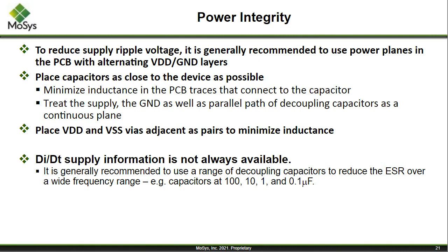And in most cases these days, I think if you look under any of the FPGA boards put out by Intel or Xilinx or anybody that's out there, people are putting capacitors literally under the device itself. And we kept the ball out of the MoSys devices at 1 mil pitch so that you could physically put a capacitor under the package, and you'll see that the ball out pattern that a lot of places are using allows a diagonal connection between a power and a ground to actually put a small capacitor in there.